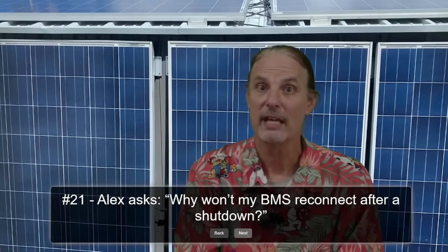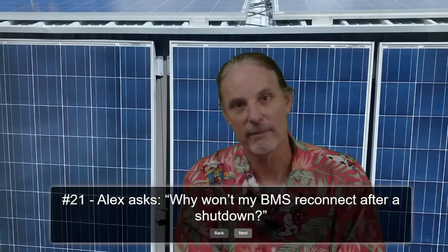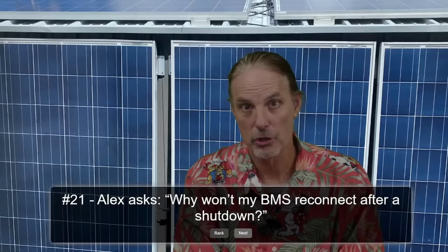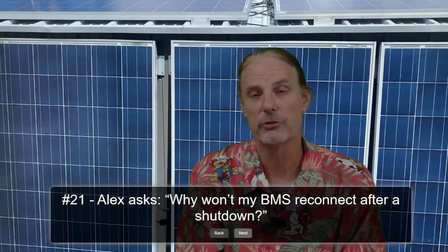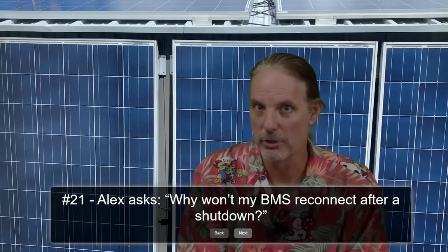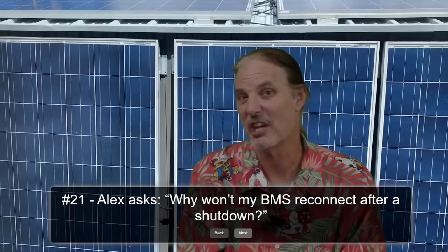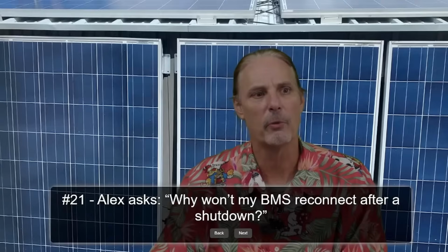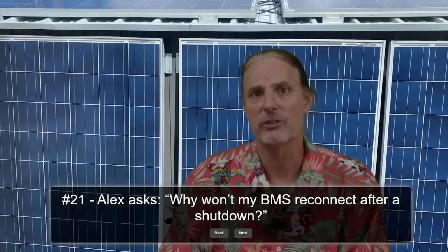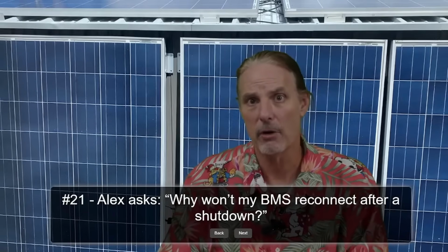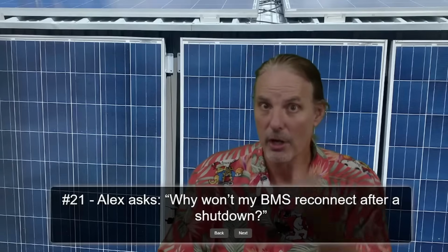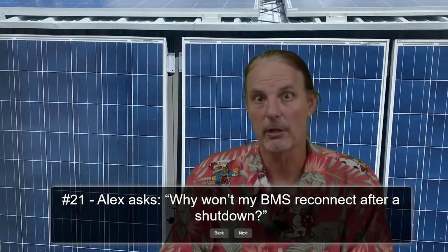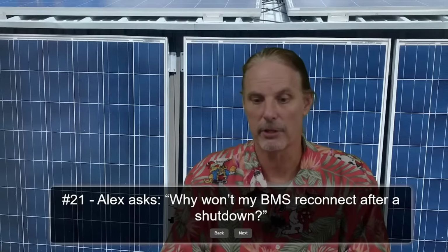When it shut down, it needed a trickle charge, and I confirmed that with a bench charger that would work, but I also confirmed that the Victron would reset it also, and I also know the 6000XP would also enable it. So several different ones there, but your battery may just not be configured to come back on correctly, or it may require human intervention depending on what kind of charger and everything that you have.